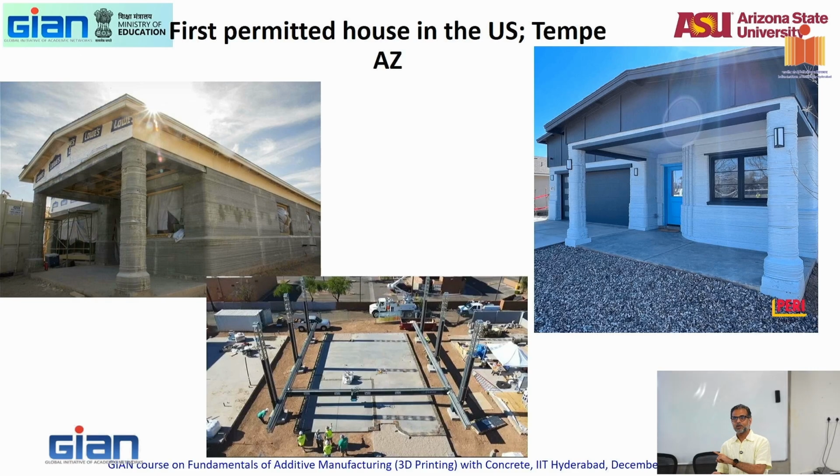The printer had to come from Europe, was stuck with customs in Texas, and did not get to Arizona till May. In May, in Arizona, temperatures go to 40 degrees Celsius. So they were trying to print this at 40 degrees Celsius, and in 4 layers, the whole thing is cracking left, right, and center. So then we had to go in and do lots of testing to change the mix and to change the curing processes. But eventually, it came out decent.